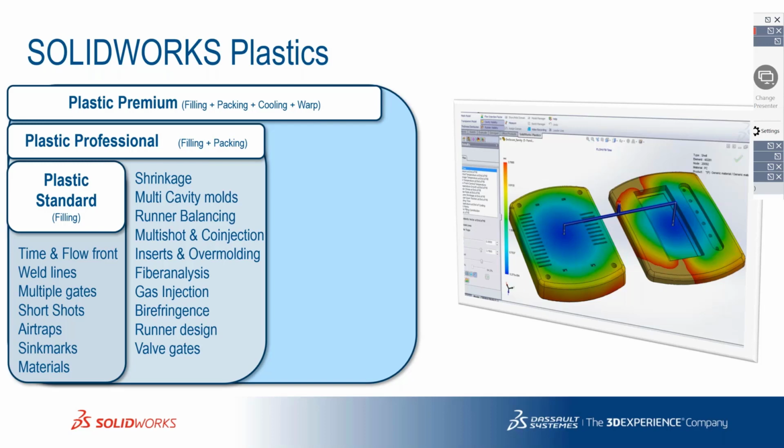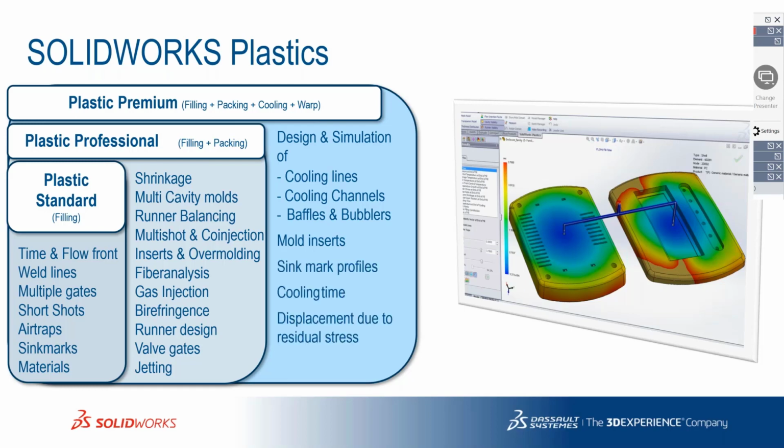So Plastics Premium has all these capabilities: filling plus packing plus cooling plus warp. I have design and simulation of cooling lines, cooling channels, mold inserts, sink mark profiles, cooling time, displacement due to residual stress, that is nothing but warpage. All these things come in Plastics Premium. Any designer who is into both plastics part and mold design, as we understand, the cooling and warpage analysis is quintessential in any mold industry. Plastics Premium would suffice the needs of every plastics manufacturing related issue.